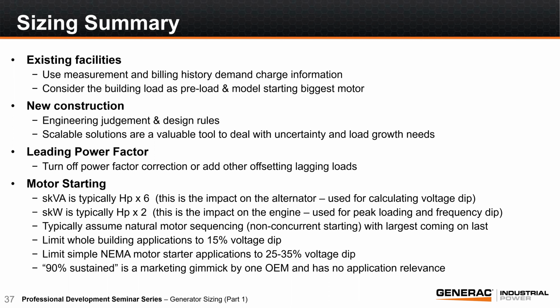We did have another question come in. You mentioned wet stacking. What is wet stacking? Wet stacking is when your generator is too lightly loaded and it results in a buildup of oil and film on the generator, which can cause the generator to fail eventually if it's not repaired. And that is when you're under, I would say, 30% load. So you want to make sure that when you're doing a sizing, you are staying above that 30% threshold to try to minimize any issues with wet stacking.